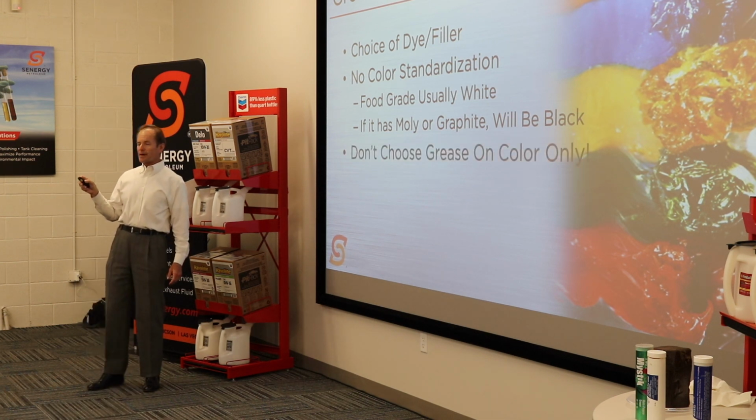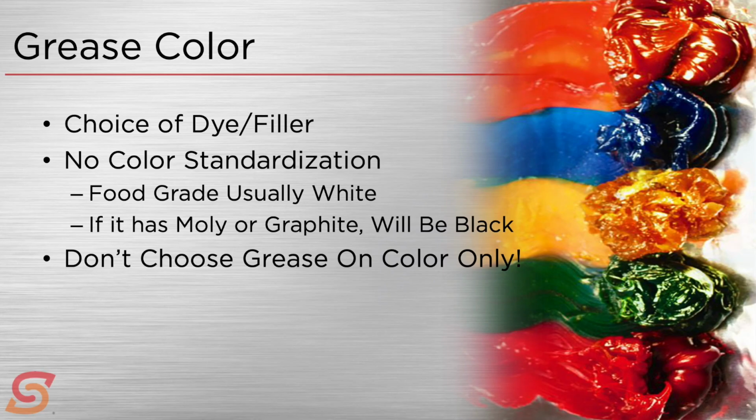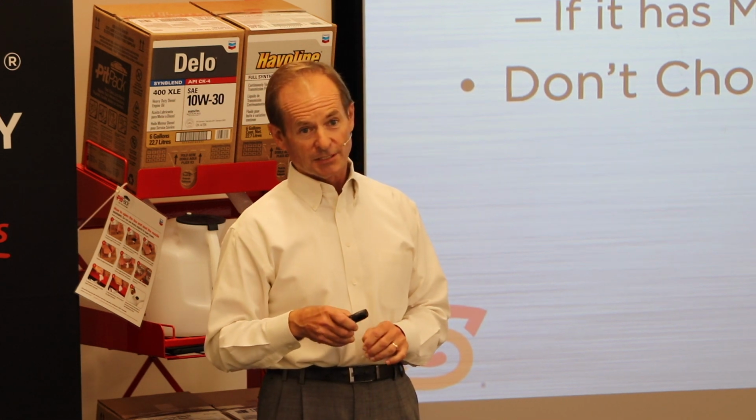I think the bottom line, and this is another takeaway from the class, don't choose a grease on its color only. Oh, you got a red grease? Oh, that's what I use. I use red grease. Okay? Grease is independent. There still may be reasons to stay with a red grease. You know, if you've got guys and they're trained to use red grease on these bearings only and there's no way to retrain them, it may have to be a consideration.